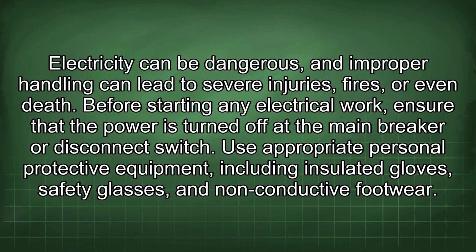Before starting any electrical work, ensure that the power is turned off at the main breaker or disconnect switch. Use appropriate personal protective equipment, including insulated gloves, safety glasses, and non-conductive footwear.